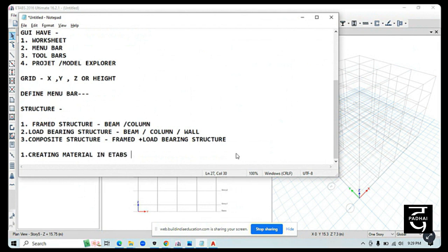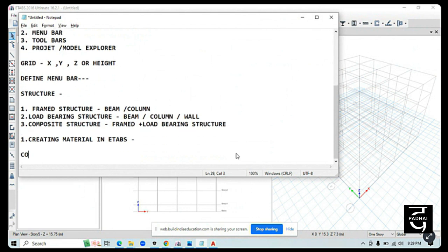In materials, suppose you are doing concrete designing or making a concrete structure, you have to go for the concrete material, right? Or if you are making steel structures or doing steel drawing, then you have to go into steel materials. So which concrete materials are available? There is M10, M20, M15 also is there, M25 also is there, M30, M35, M40, and from M40 it goes along till M80. Okay, so you can see when you go above M30, these all come under precast structure.